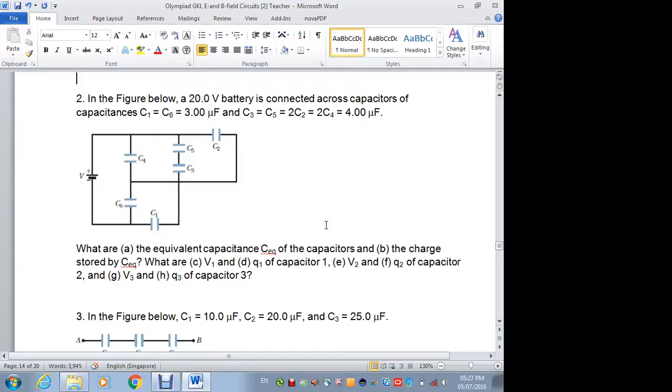Okay, so when you see this type of circuit, you have to redraw. Now, one way, right? This one doesn't suit your orientation, you just flip. Right, just do that. Okay? Then you'll see that actually this part will be in series with the upper part. Right.